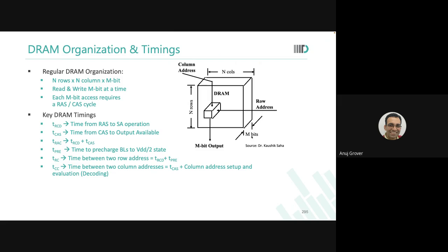In addition to that, what we also need to see is that in every array, by virtue of giving RAS and CAS, I will select one bit and one bit only. And when it comes to multiple bits, we're talking about, logically speaking, the depth of that cube.